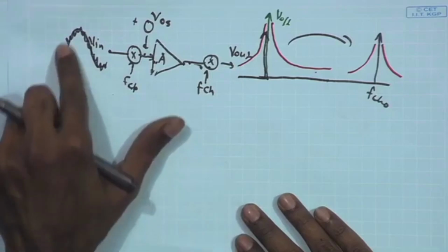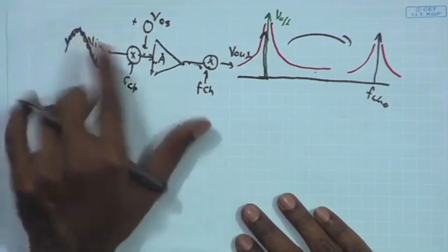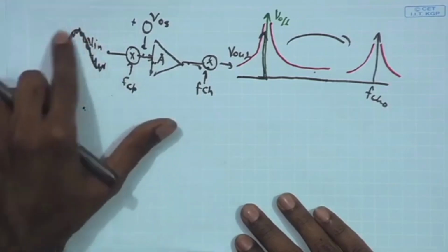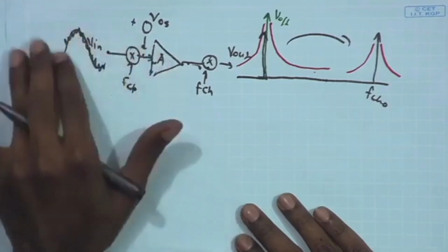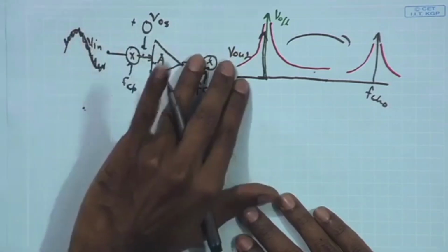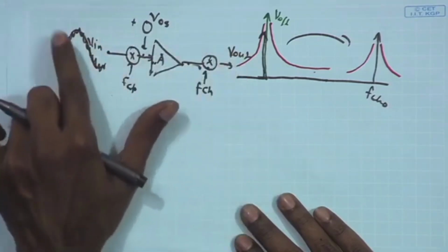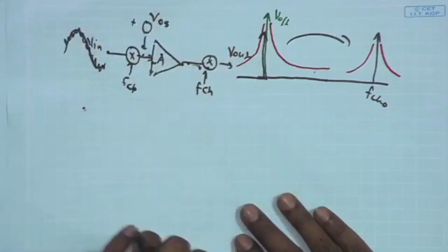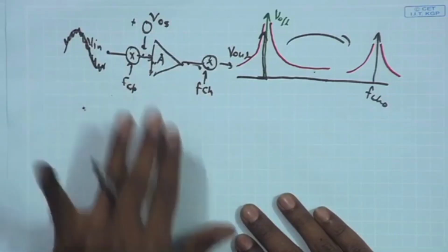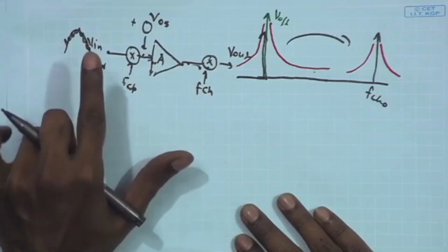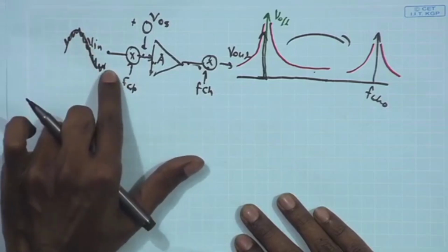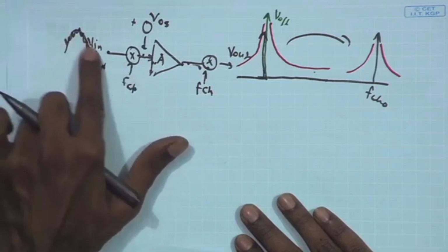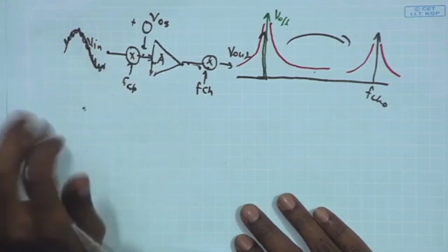So, basically, if you have a feedback factor beta given by 1, and the A beta is much larger, therefore, the gain can be at least set to 1. So, for this particular dynamic offset, the gain can be set to 1 if I have a strong enough feedback, beta equal to 1, in the negative loop. But in that feedback loop I would set the cutoff frequency so low that the actual signal is not able to pass, only the slowly varying dynamic offset, the undesired large amplitude dynamic offset, is able to pass. For that,